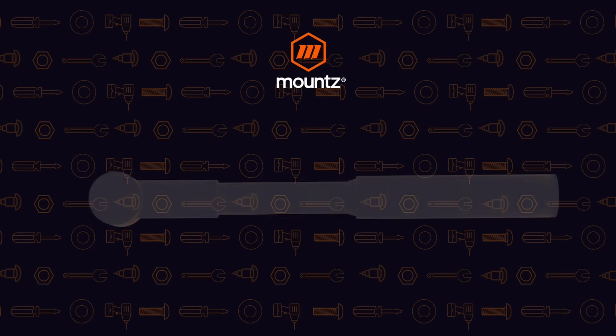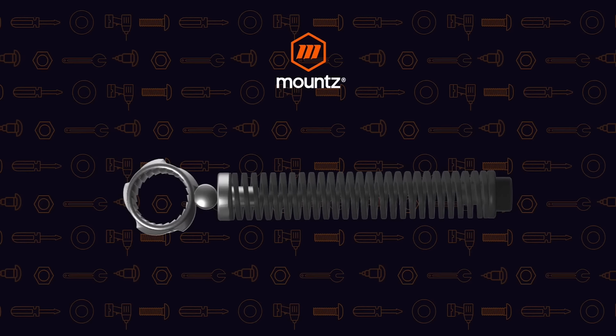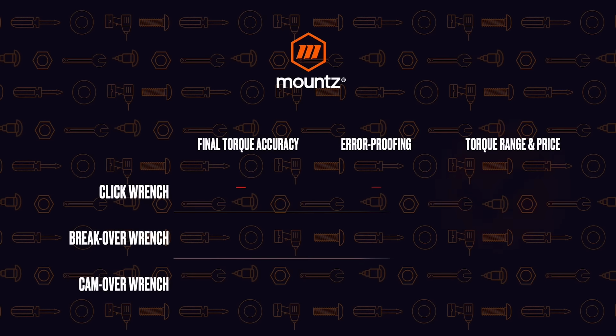And so if we looked at that particular operation within the animation here, you can see that very similar to the torque screwdriver, as the cam is turned or the drive is turned, it's going to push in on the follower, compress the spring to a certain point, and then the cam will reset. So we can never add any more torque than what is necessary for that particular application.